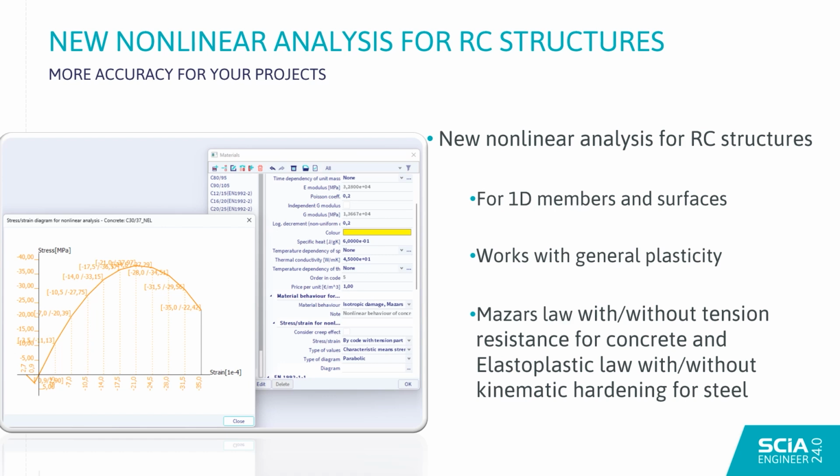Not only that, but it will also support, of course, general plasticity, and it will support the new Mazars law with or without tension resistance for concrete, and elastoplastic law with or without kinematic hardening for steel.